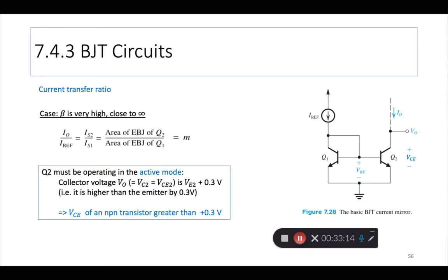But truly, looking at how the world of electronics is evolving, because of the great advantages of MOS and CMOS, most amplification circuits and ICs, even analog circuits, tend to be MOS based technology. So having said that, let's quickly look at BJT circuits. Now the problem with BJT is that this beta is a very variable thing between transistors of the same family, and they can mess things up.